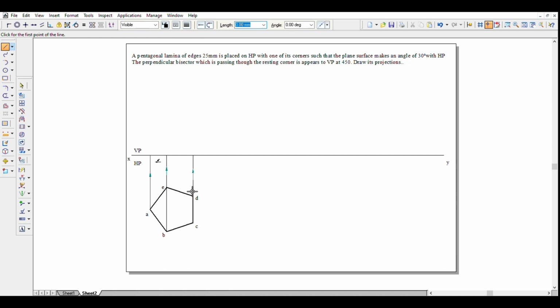to mark out the distance, until the given inclination of 30 degrees. So what we'll do, we'll select along with the annotation, we'll select this line and we will use the move tool, but we'll make a copy. So we'll select the endpoint and place it a little away on the line. Now we'll use the rotate tool. We have to specify a starting point and an ending point, the start of this line to the end of this line. Now when we click tab and enter the angle we want it to be tilted in, 30 degrees, the line is automatically flipped into the 30 degrees.